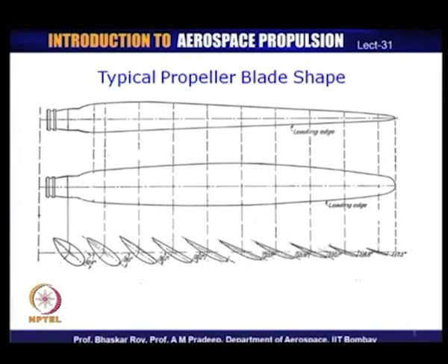Now, as we have seen, choice of these aerofoils, setting of these aerofoils together and blending them into one blade shape create an efficient propeller blade, which should be efficient during all times of its operation. Of course, as we know today, all propeller blades are under variable pitch operating controls, and as a result most of the propellers do have variable pitch controls normally associated with the propeller operation.